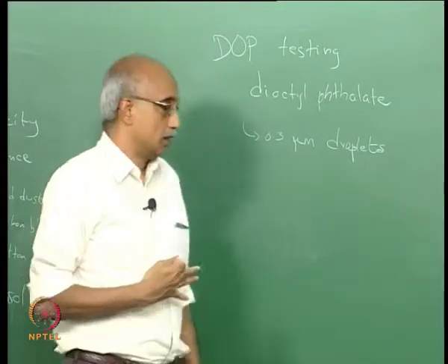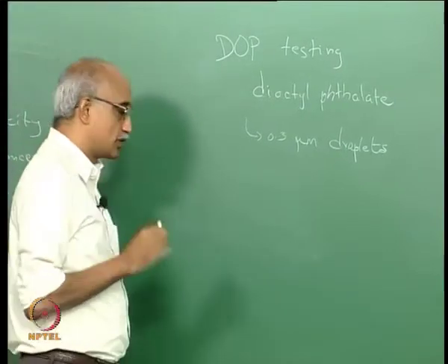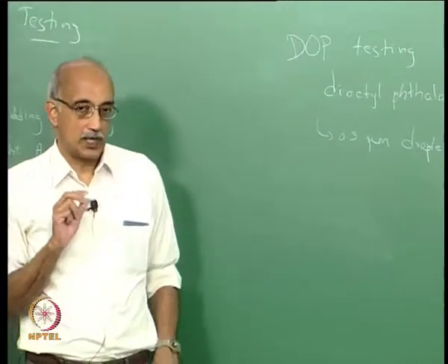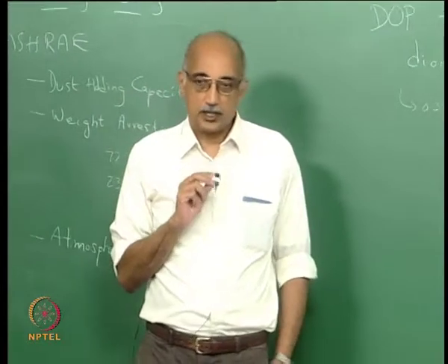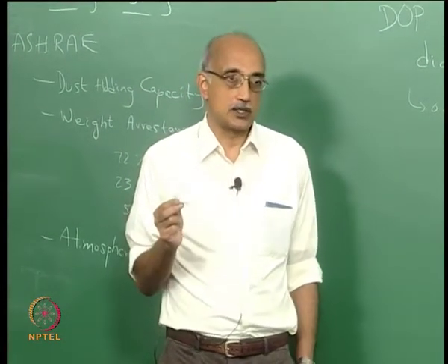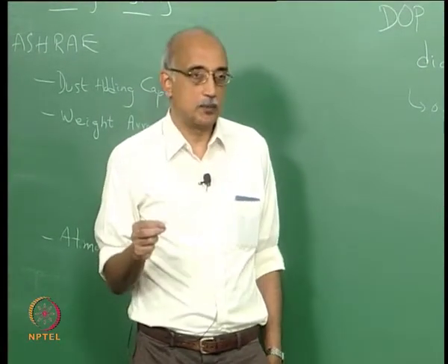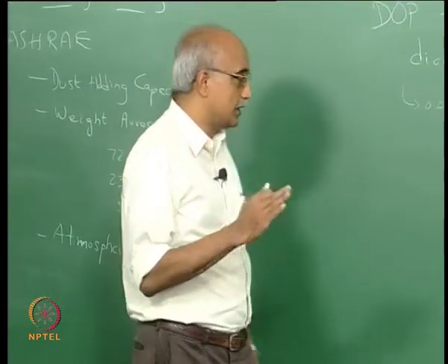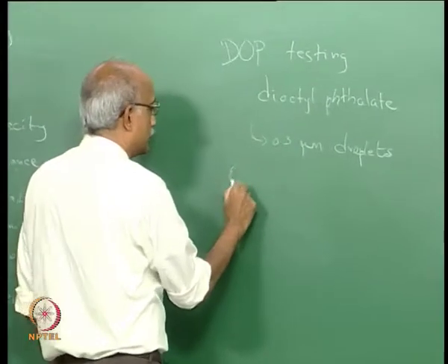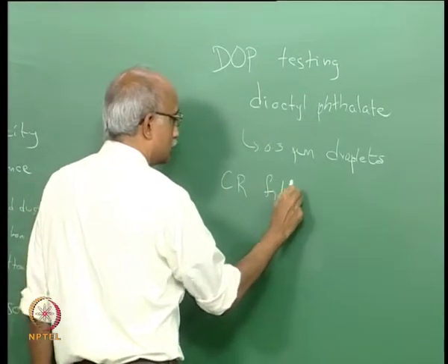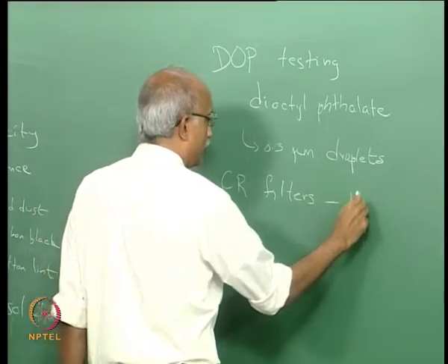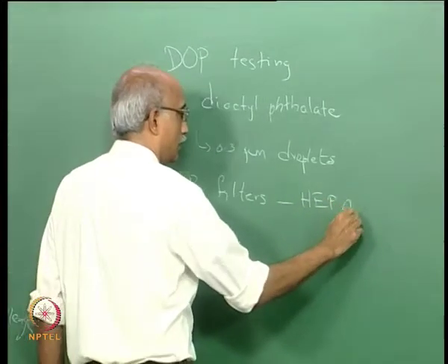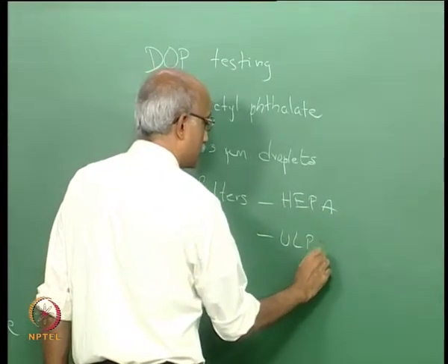When you start characterizing filters at this level, these filters are typically used for clean room applications, where it is very critical to maintain particulate cleanliness of the environment. And there are really two types of clean room filters: HEPA filters and ULPA filters.